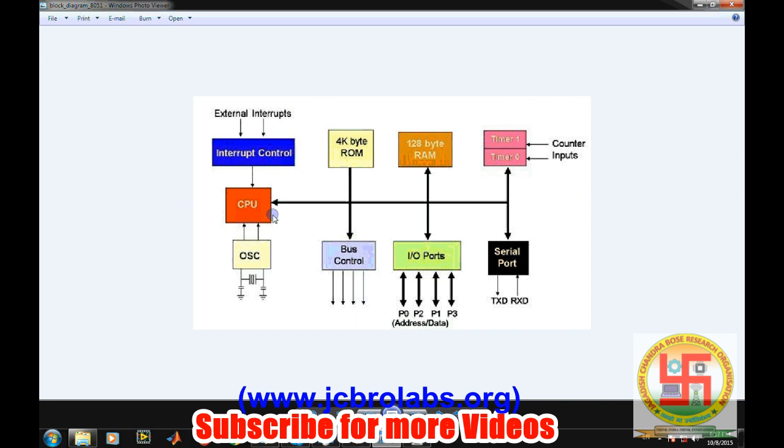The different registers used in the CPU are stored in the lower 128 bytes of RAM, while special function registers like the accumulator, B register, different port addresses, registers for timers and serial port communication, and registers for the program counter and stack pointer are stored in the upper 128 bytes. We will go into further detail of this RAM, because that is particularly important when we talk about writing assembly language programs for the 8051 microcontroller.